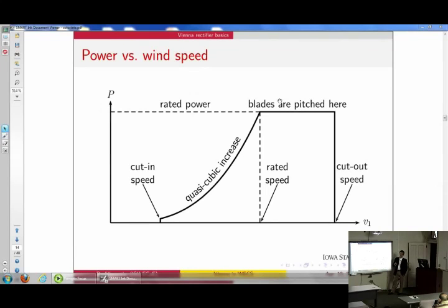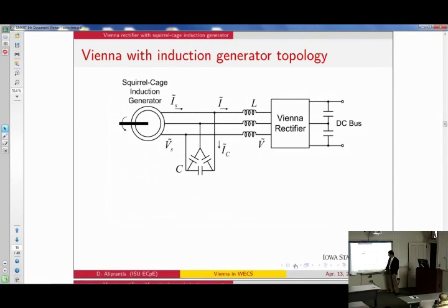And why is that? Because typically large wind turbines have a lot of inertia, so as the wind speed changes, you're basically always, electrically speaking, in some steady state. You just move around slowly, following the change of speed of the blades and the rotor, which has a big inertia, so it does not accelerate and decelerate very fast. The time scales are different. So the analysis will be on a steady state basis.